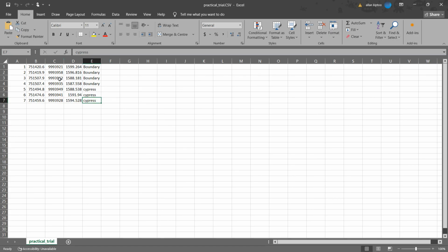When you look at this data here in Excel, what you realize is that the first column has the point ID. The next columns have the eastings, the northings, the elevation of that area, and then the description. It's important for you to know the format of your data, because in some other cases you'll have the northings first and then the eastings. These formats are good because AutoCAD can easily read them.